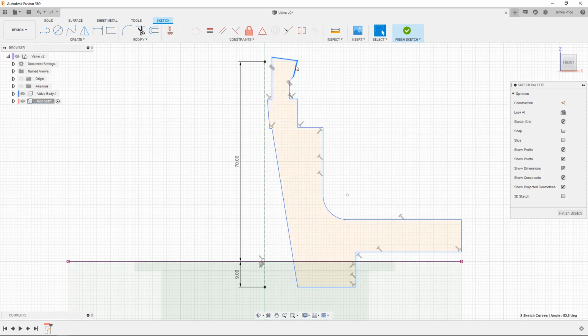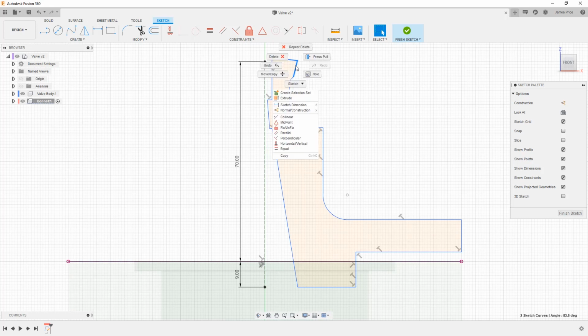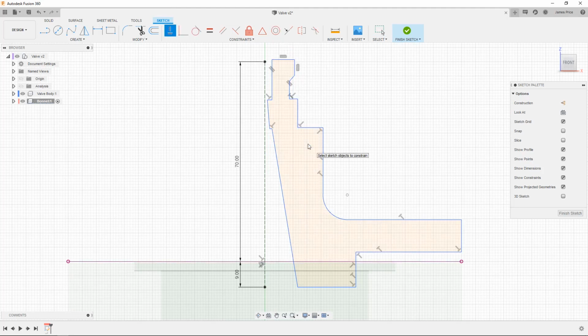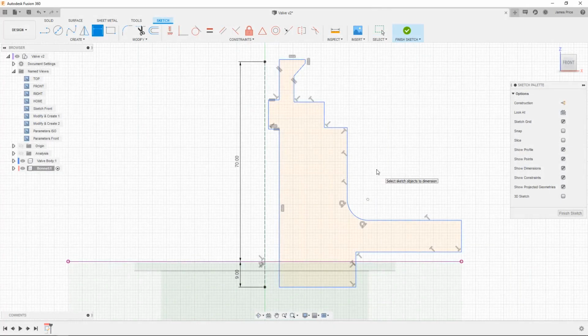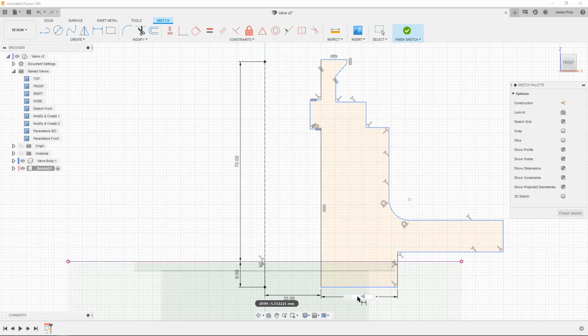One quick tip here is if you select 2 sketch features and right-click, you will only see constraints that are respective to those sketch features, which can help save you some modelling time. Alternatively, you can apply any number of constraints via the toolbar, as well as sketch modifications including fillets and offsets, and dimensions, also known as smart dimensions in SOLIDWORKS, by either selecting the command or the features first, then applying until you have a fully constrained model.